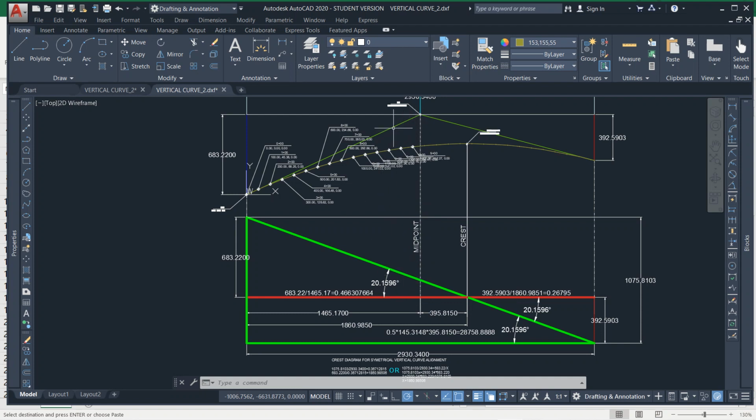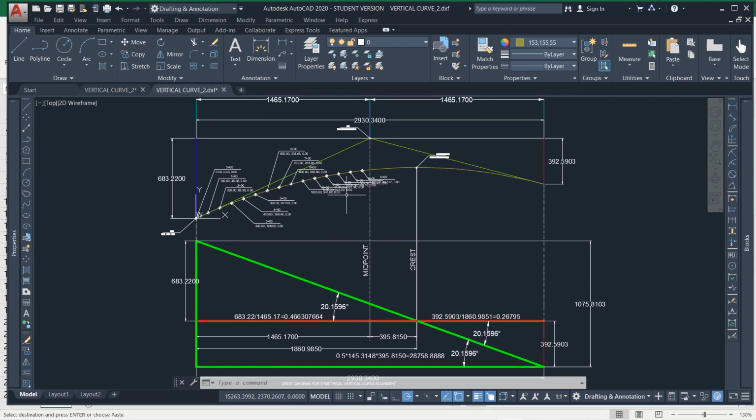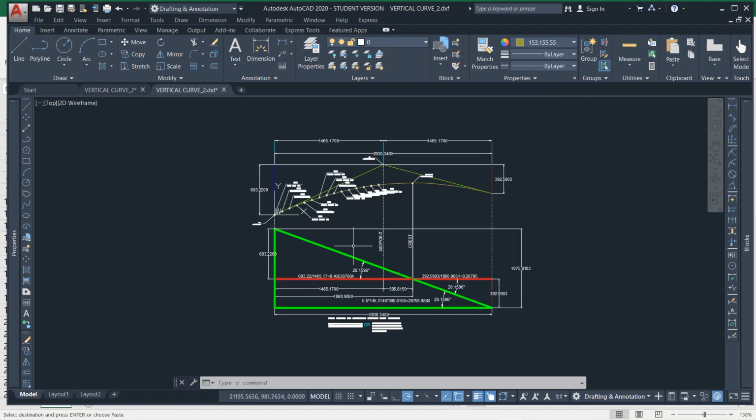Let's say this is the PVI, the center, and you got the area, the triangle there, you would be able to use that area as the vertical rise. But it's a lot of work a lot of times to get information, but it'd be kind of useful if you forgot the formula and you were on an exam. And it's very delicate too, so you have to carry out the decimal places very far to get an accurate number. And that's what I know about vertical curve alignments.